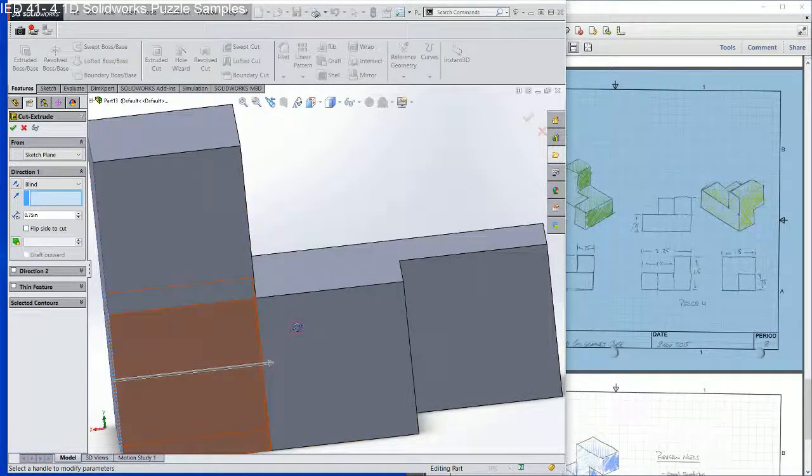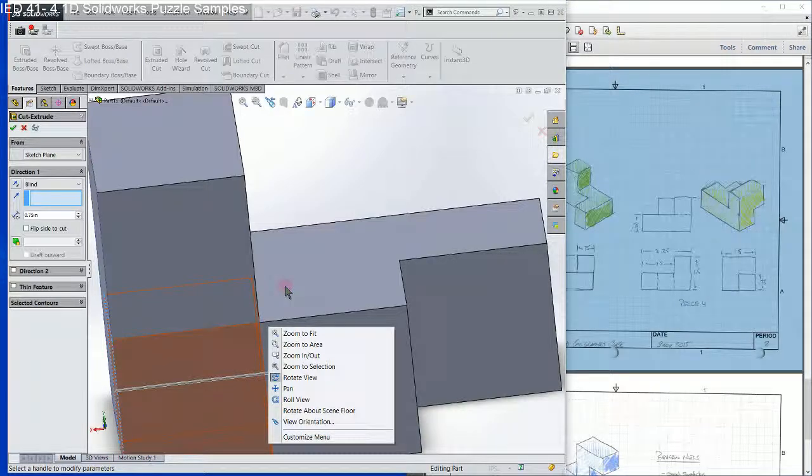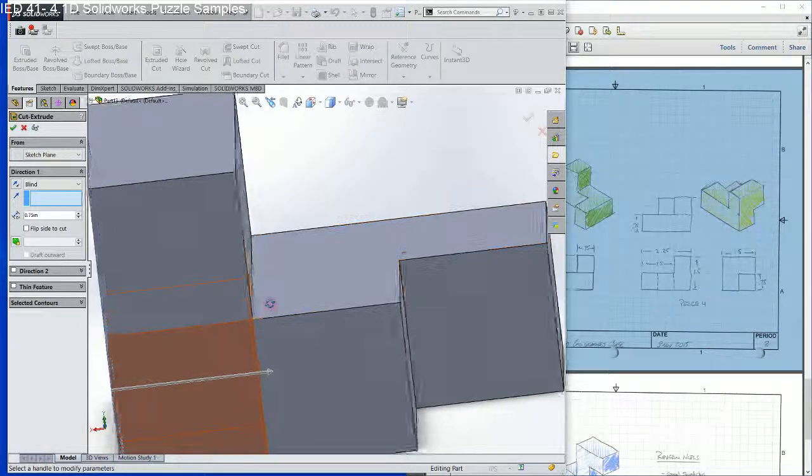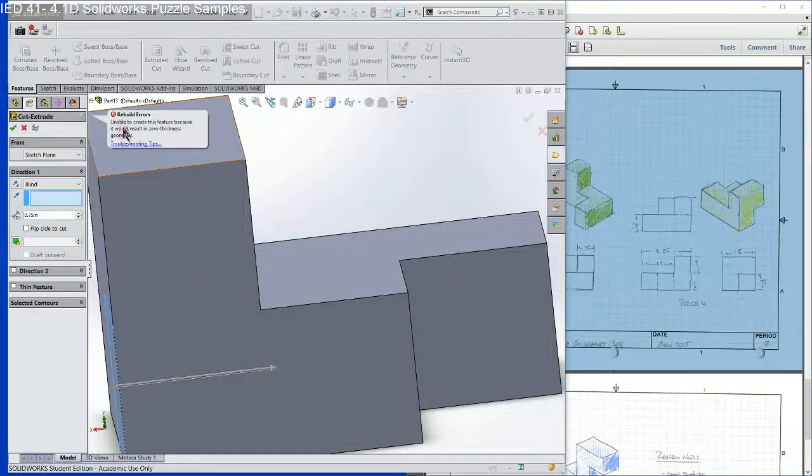the gray square meet. And what Solidworks is telling you is, hey, I can't really make that cut. And I can't make that cut because it's mathematically impossible to have these two meet at that point and have 0 thickness. So I can make my cut a little thin, which is what I'm going to do. Let me show you the message it gives you when you do that. It tells me, hey, look, unable to create a zero thickness geometry. So you can go click on that X,